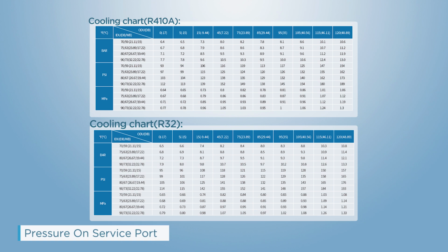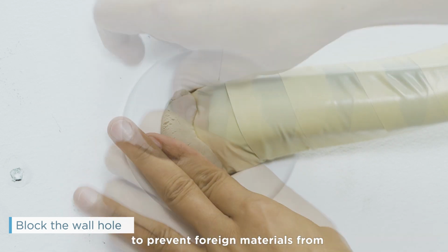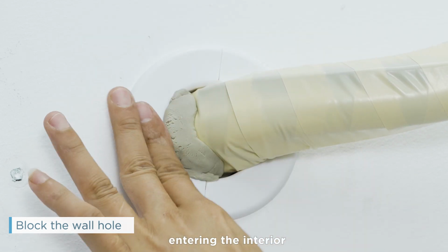Pressure on service port. Use damping adhesive to seal the wall hole to prevent foreign materials from entering the interior.